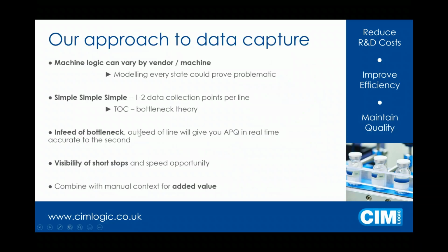And that's where we come into our approach on data capture. So yes, you can connect to every machine on the shop floor, and yes, you can get every tag out of the machine on the shop floor. If you're putting an OEE data capture system in, for example, you'll want to know when the machine went into a stopped or a starved or a blocked state. But you might not necessarily need to know that it went into that stopped state because machine door number 3 was opened. Yes, you can get all of this information from the PLCs on the shop floor, but you need to combine it with some context from the operators.